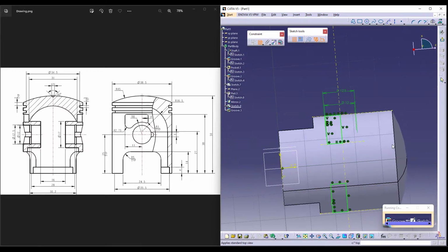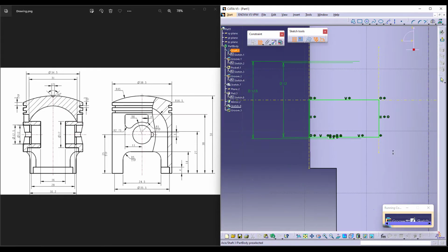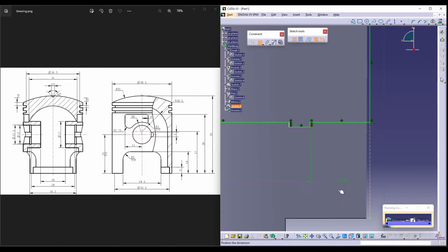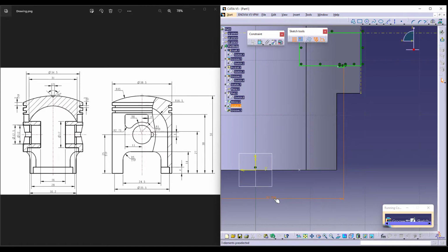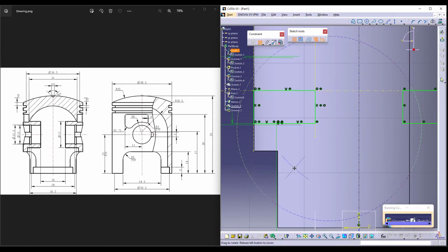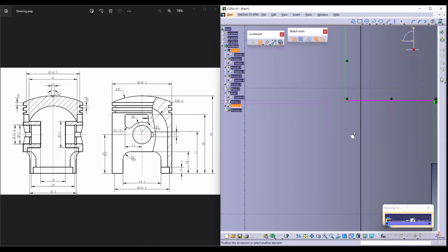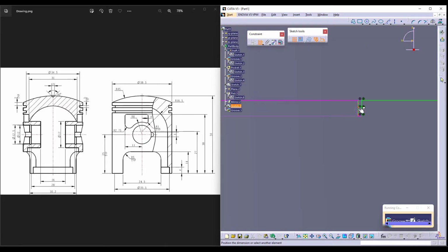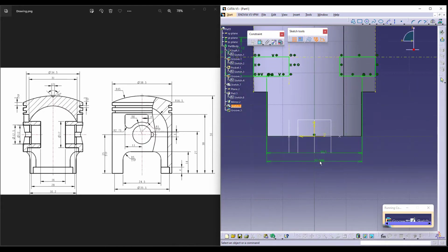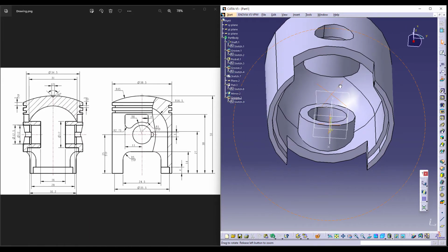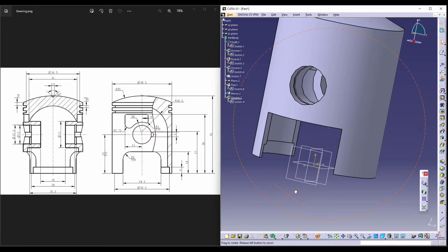Let me take the right view for better understanding. Now the distance between the outer part, as in this to the outer part of this feature, is supposed to be 30.2. Now from inner to inner is supposed to be 28. From this to the inner feature, which is this, is supposed to be 28. Now once I exit, it creates a groove inside the existing wall. This is your groove cut.